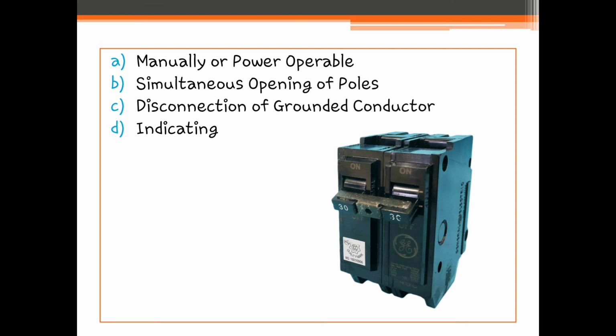Next is simultaneous opening of poles. So ang mga buildings or structure disconnecting means shall simultaneously disconnect all underground supply conductors that it controls from the building or structure wiring system.